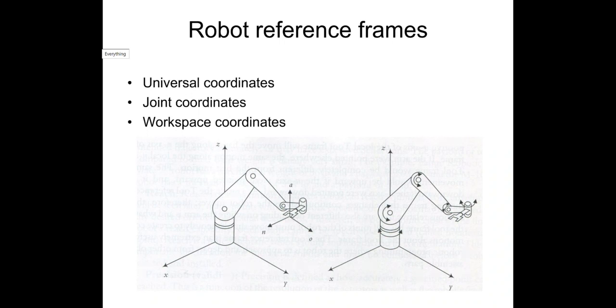Let's take a look at this figure. For the one on the left, let's do a quick analysis of the joints it has. Right here on this robot, there is obviously a revolute joint, which means the robot can rotate in this direction, around the z-axis. And right here there is another joint, which is obviously also a revolute joint. Let me call it R for revolute joint.